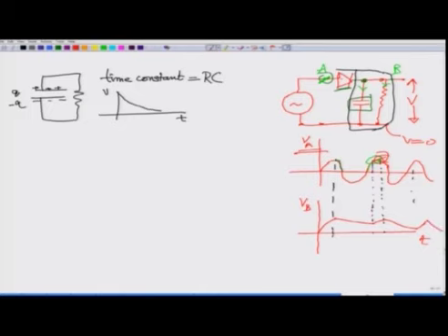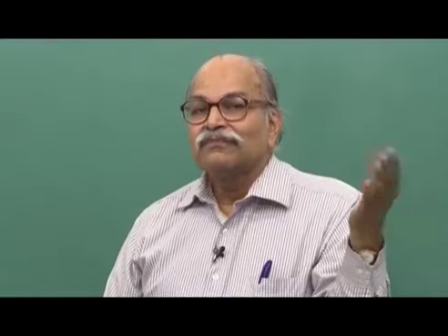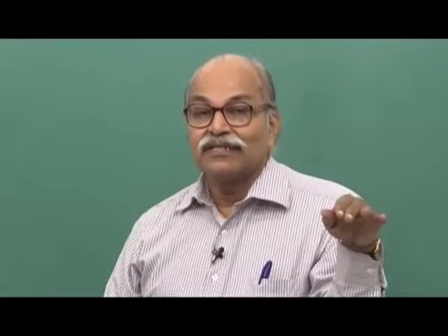So, compare this with the case when we did not have any capacitor. At that time the voltage diagram at B was of this type. This was VB as a function of time and now it is this, and you can see that it is a better DC. This was a very poor DC, very bad DC. It was unidirectional, but if you look at the voltage, it is far from that ideal constant voltage situation.